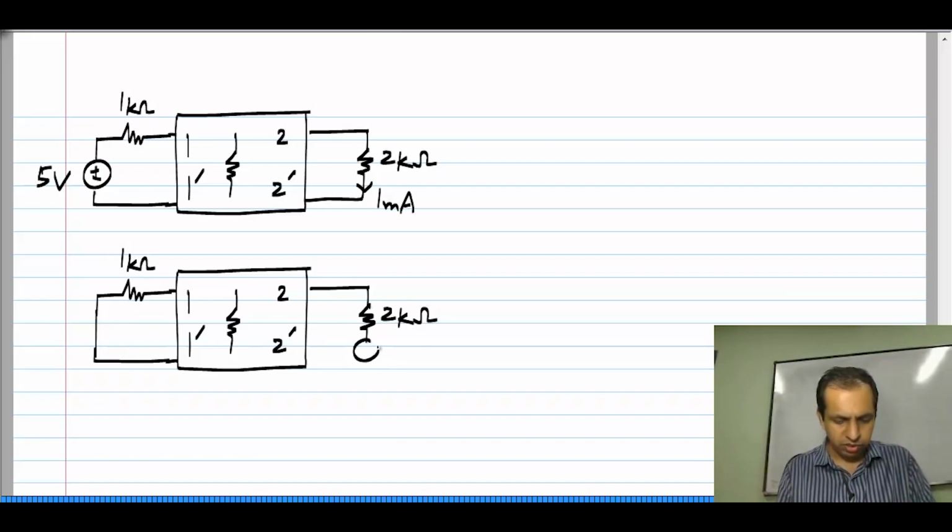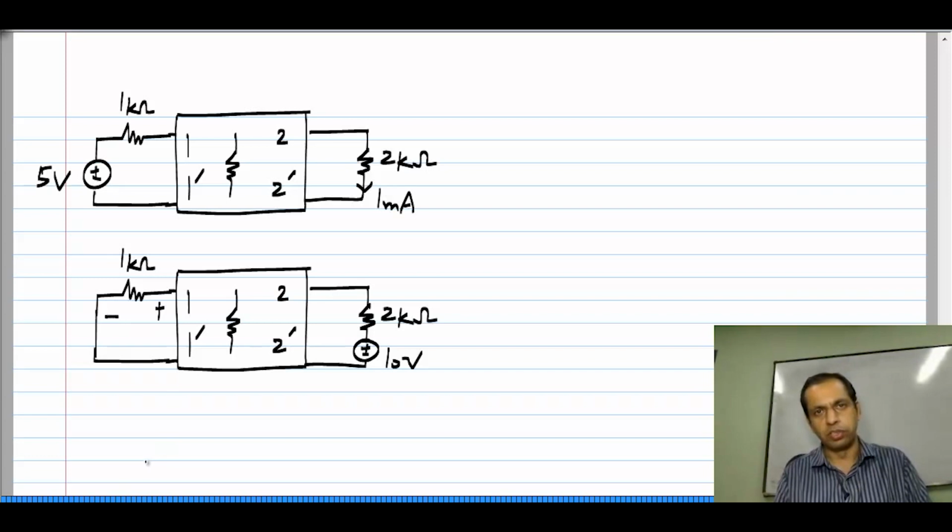And then let us say you are asked this question, I apply 10 volts over there, what is the voltage drop across this 1 kilo ohm resistor. Now, this looks slightly more complicated. Now, one thing you can of course do is, because this is a resistive network, you can describe it with a 2-port parameter set, whichever it is, and apply the reciprocity constraint, that is Y12 equals Y21 or Z12 equals Z21 and so on. Now, the better thing to do is to realize that this is exactly the same problem as before in slight disguise. I will define my new 2-port to be